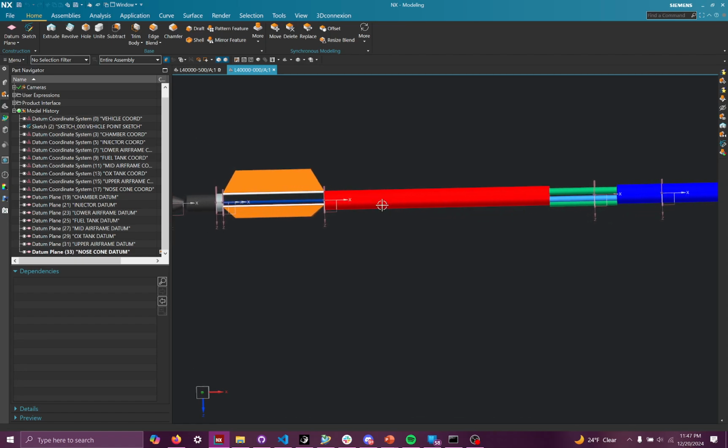Firstly, the reason why it didn't update automatically is I don't have these files loaded. As I said at the beginning, I just freshly opened up NX, and I didn't open up any other files between the vehicle assembly file and this vehicle layout file. So none of the other layout files or assembly files are loaded. And that's really the root of the problem.